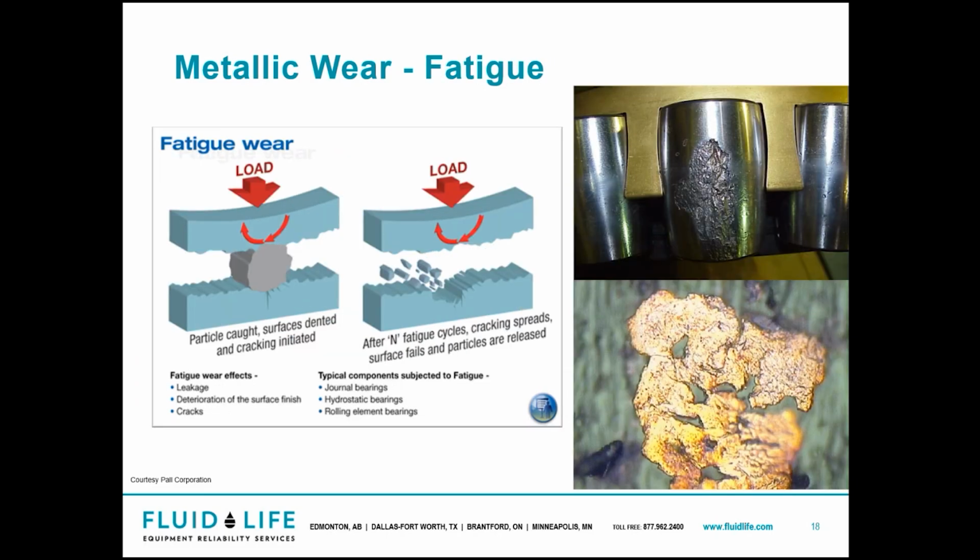Now, equipment gets old and broken, as do we all. So what happens with fatigue? It typically occurs when a piece of equipment has been overloaded. So equipment, especially something like roller bearings, goes through elastic deformation. Elastic deformation is when load is pressed onto it and it compresses, like for example the roller elements, and then it goes back to its same shape. That's just the natural cyclic loading of elastic deformation.